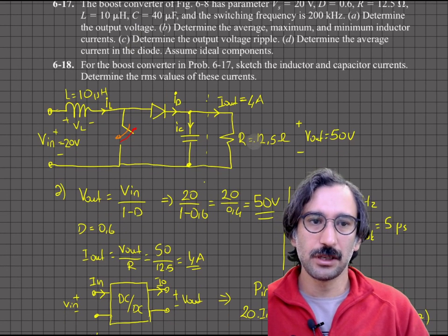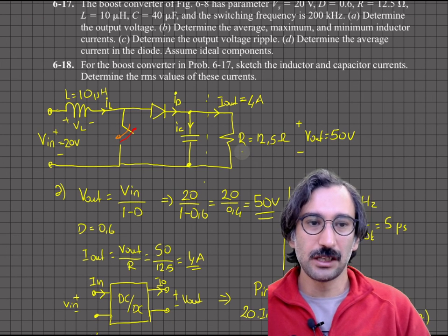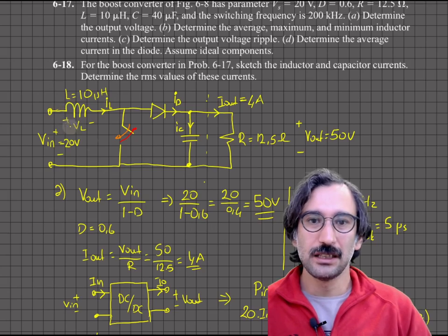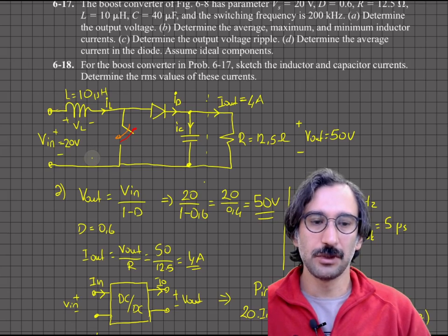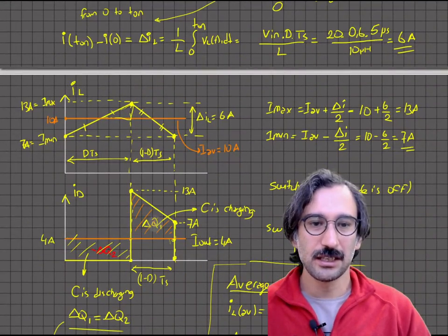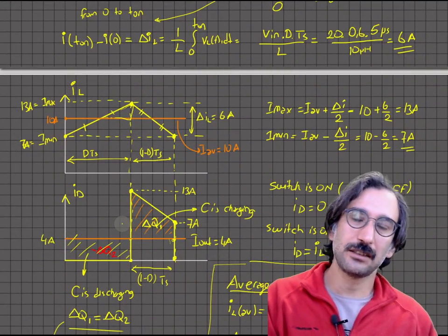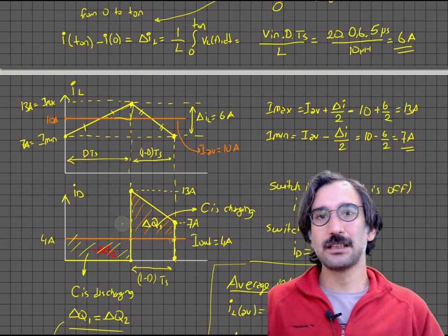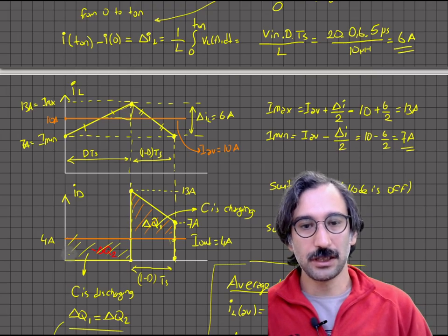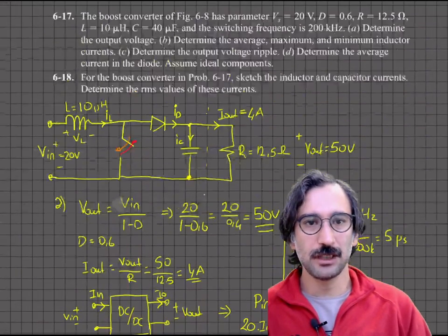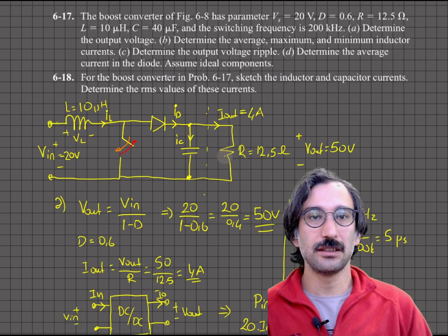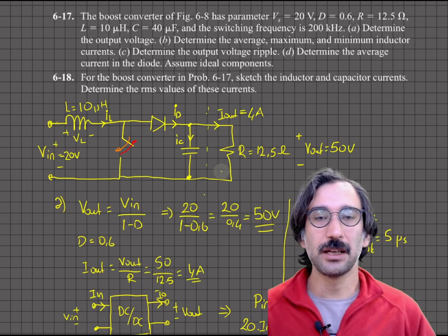So be careful about the output current levels. The amount of current sent from the output is not equal to the current drawn from the supply, and the excess amount of current is being used to charge the capacitor, so that it can use that extra charge to supply the load. Because during that time, when you are charging your inductor, basically the capacitor is just by itself supplying the load.